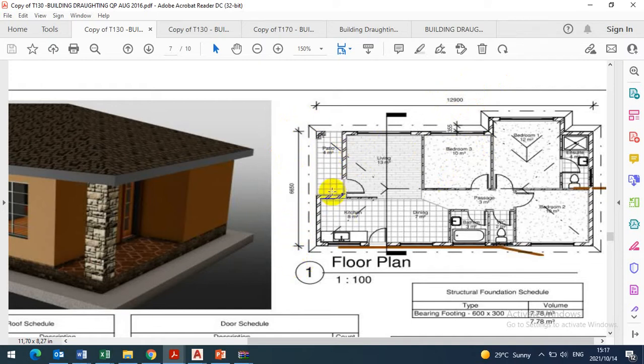There are two rooms for this side. For the patio, I've used 2,900 from outside to here. There's 220 here. I need to add 220 plus the length of the patio plus this 220 plus the length I'll use for the kitchen, corner to corner, whatever length gives me 8 square meters. When I multiply with this other length and add 220 with that length and another 220 here, I get 6,650. So it is a technique that you have to work with.